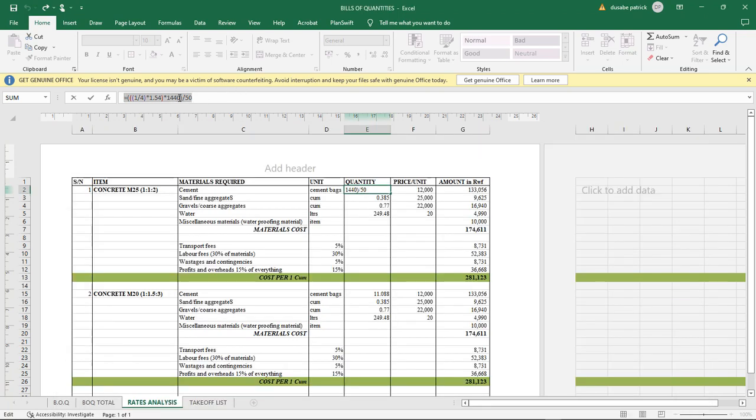So we just multiply the density of the cement, and then at this point, we'll be having just the kilograms of the cement. And then after that, we know that the cement is packed within the 50 kilogram sacks or bags. So we divide it by 50 so that we can get the cement bags. So about here, we're gonna be doing the same. I'm not going to delete everything because this will just take us a little bit longer. So I'm gonna be changing just the numbers.